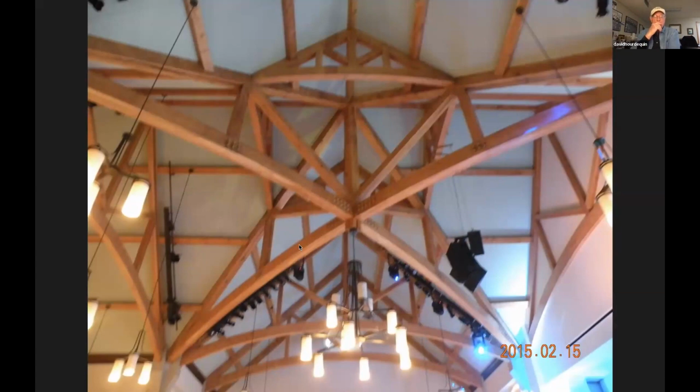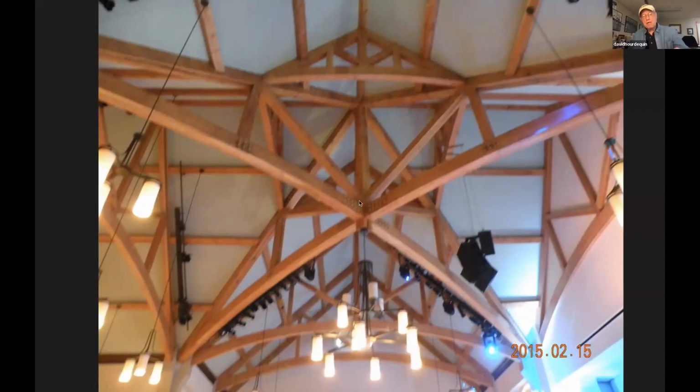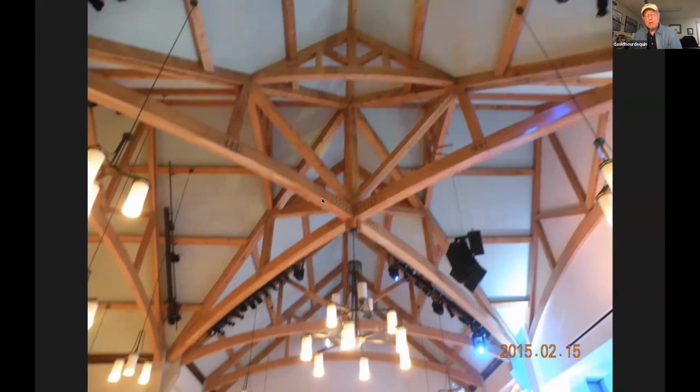The other is, and I'm going to slide off into an adjacent area, but when you're designing kerf plate connections with bolts or pins, you can use steel pins or bolts, either one, like these are. If you have green timber, you cannot put two rows of bolts on a common plate, because as the timber shrinks, it will split either down one of the rows or in between them or something like that. And so the capacity of each bolt has to be reduced to 40% of its nominal capacity.